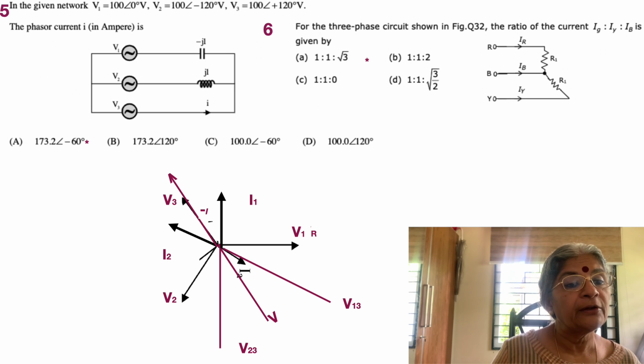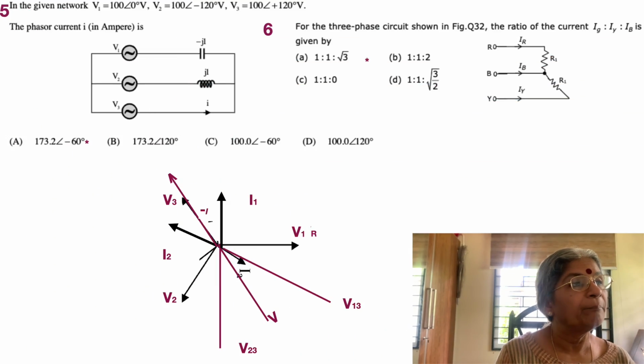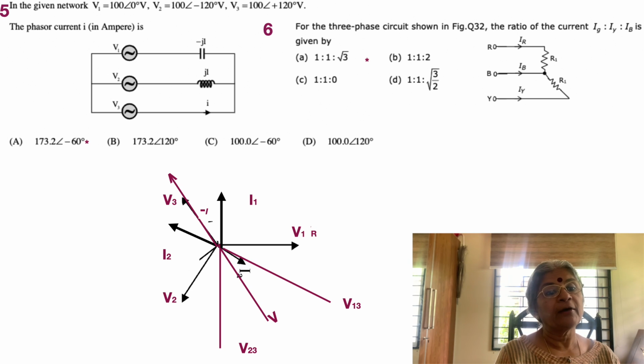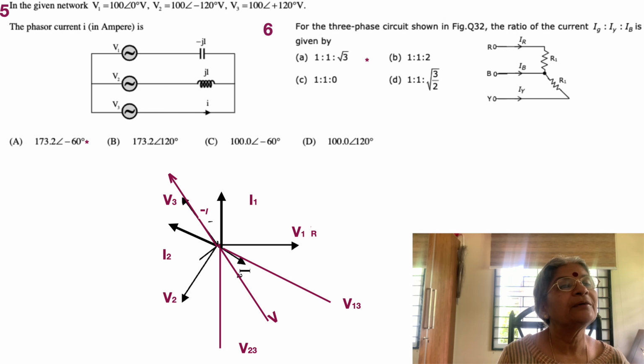For instance, when you're dividing by the capacitance for V13, you are going to have an angle of minus 90 degrees in the denominator, or a positive angle, in other words a counterclockwise direction for the current. So I1 is set at 90 degrees with respect to V13. On the other hand, when you're looking at V23 and the current driven from the source voltage at 2, you see that there is a lagging current. Why? Because it's an inductor, of 90 degrees. So just take back the current, and you see that there is 60 degrees between them.